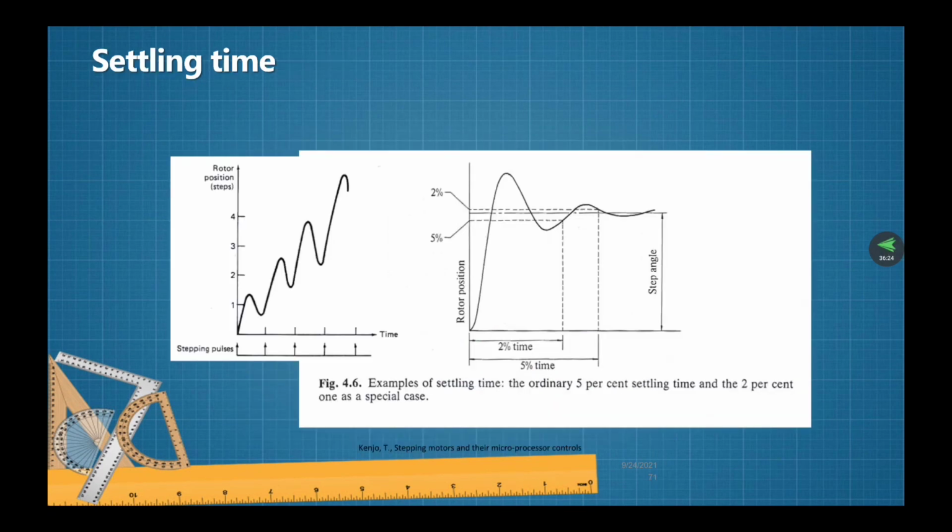In operation, the slightly sagging magnetic field acts as a spring, with audible noise due to the stepping. So if vibration at low speeds is an issue, consider geared types. Not only does changing the gears increase torque, but it also improves starting and stopping responsiveness.